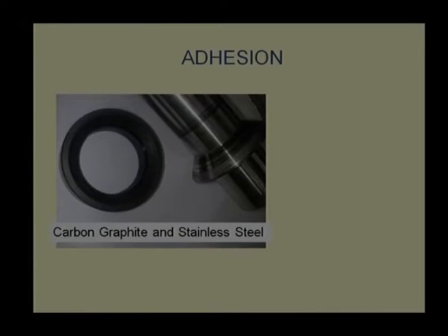That is a strange thing, because this is made of the powder form, and when it is rubbed, what will happen? It will leave its prints on the shaft. That means one layer will be transferred. So, this surface is transferring this carbon layer, graphite layer on the surface. It is an interesting thing, people have experience that adhesion to some extent can play a good lubricant role.